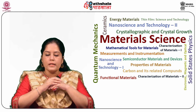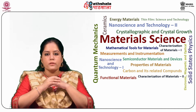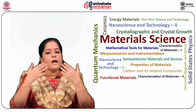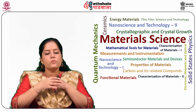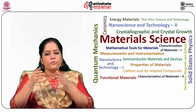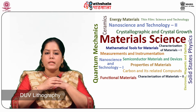EUV lithography uses photons with 13.5 nanometer wavelength to expose wafers. It has higher resolution with suitable numerical aperture than longer wavelength photons used in conventional deep UV lithography.